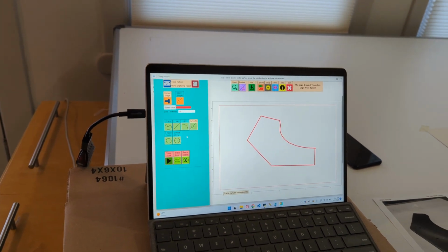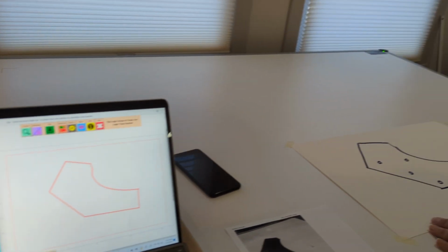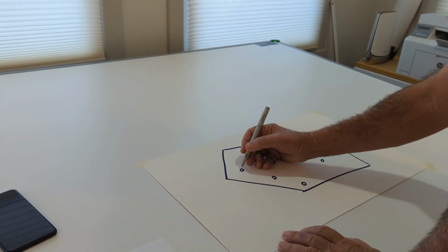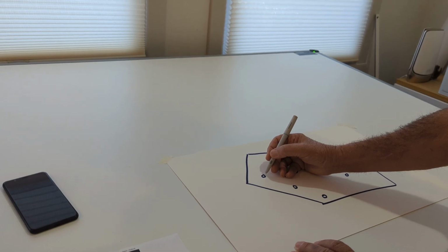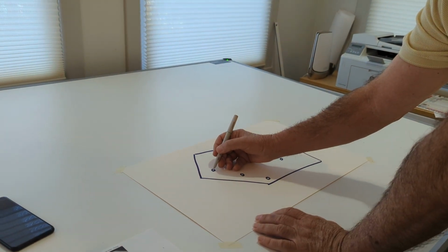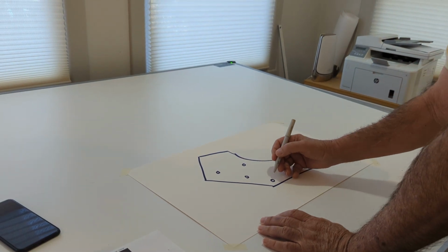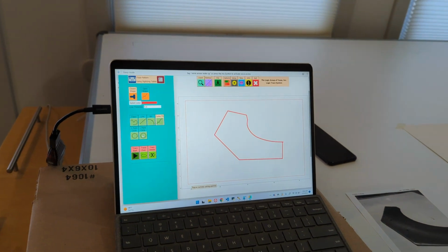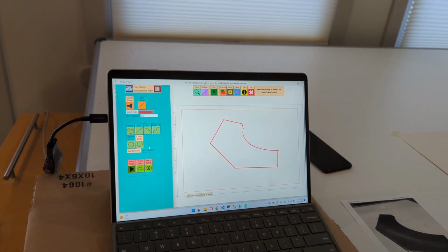Now on the circles, usually what I like to do to a circle is to digitize 3 points on the edge of the circle, and it pops in a circle. This time what I'm going to do though is I'm going to say, okay, I think I know where the center of each of the circles is, and I'm just going to do the center point and input a diameter. So in our software, that's a 1-point circle. I click 1-point circle.